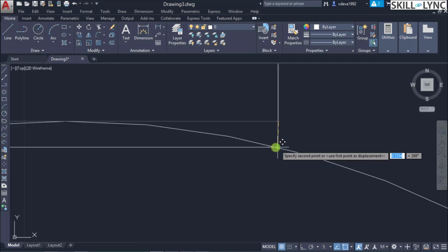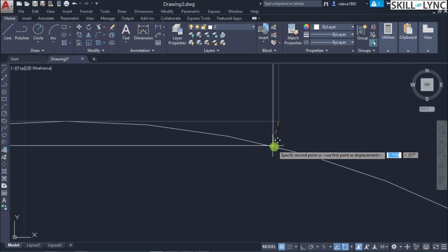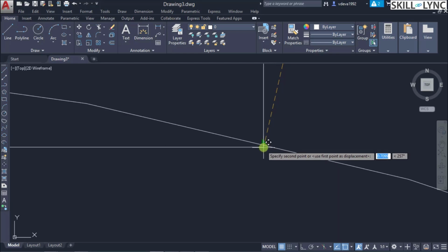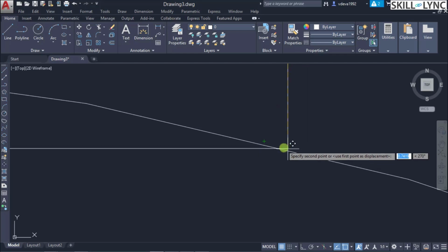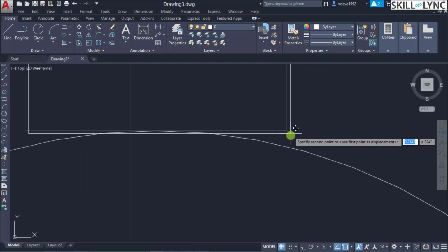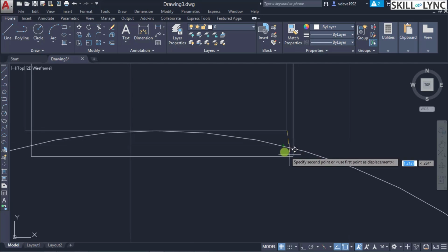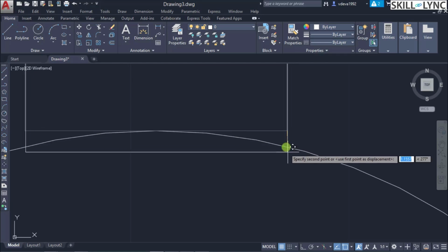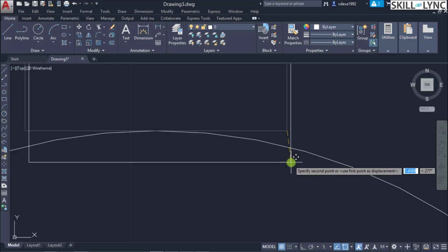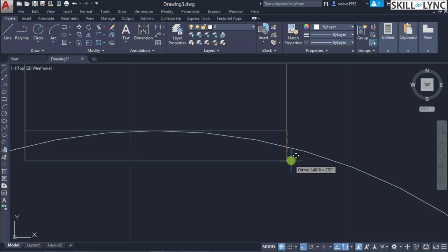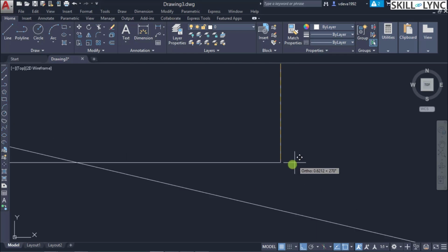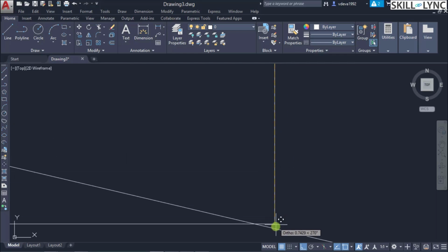But as you could see, the snapping is snapping onto the perpendicular point, but then it always shows the nearest point. Our objective is it has to be positioned perpendicularly down. So let us turn on ortho snapping, that is F8. Once you have done that, it will ensure that the snap stays to here, and you can see the nearest point is taken as here.